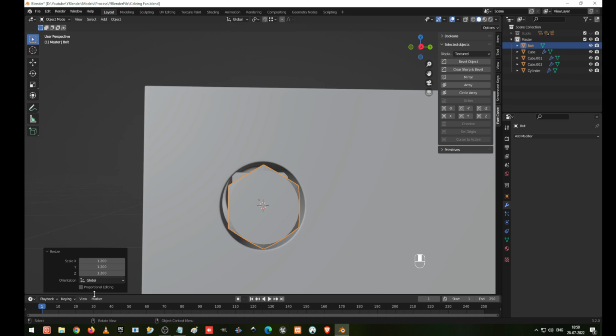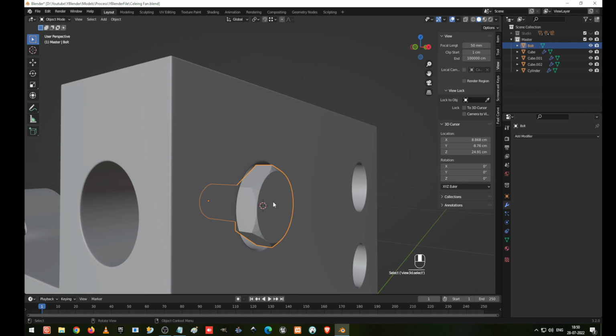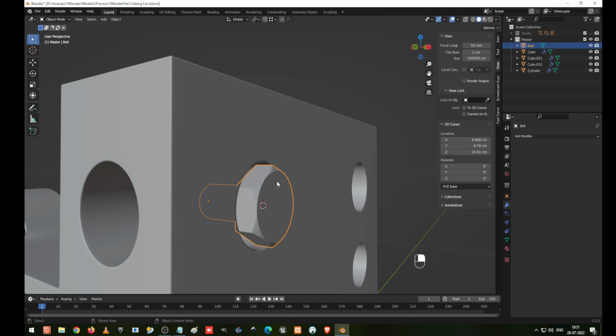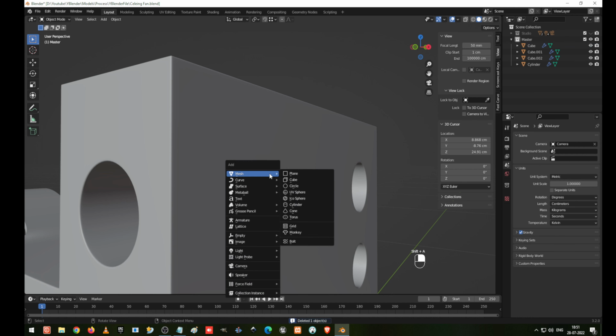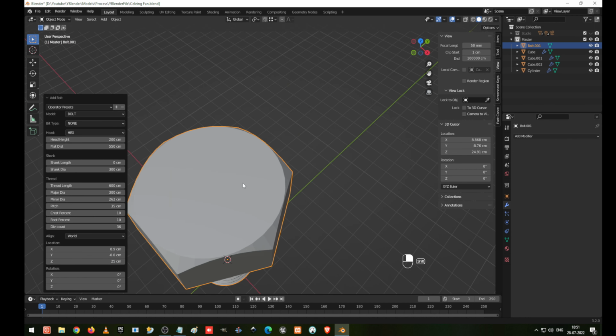So here we are going to modify this. Okay, I made a mistake again. So let's go to the Bolt Factory tools. Okay, I need to do some settings before adding this. Go right click and go to... okay, it does not come. So I do one thing, I press Shift A once again, go to Bolt Factory, and before doing any changes I'm going to do this setup.